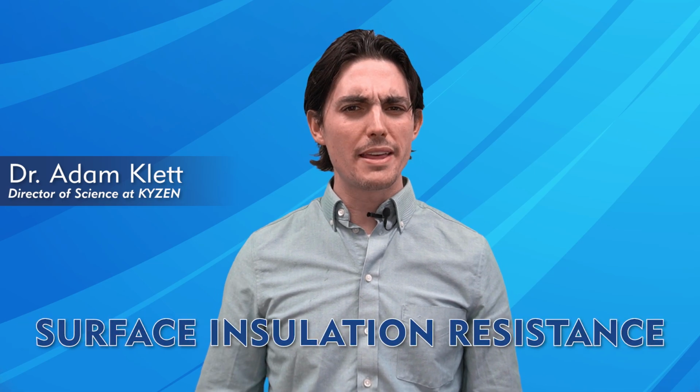SIR, or surface insulation resistance, is a method for us to determine how clean our circuit assemblies are. It's called out in IPC standards as a method for us to provide objective evidence needed to qualify a cleaning process. For most people, that process looks something like this.